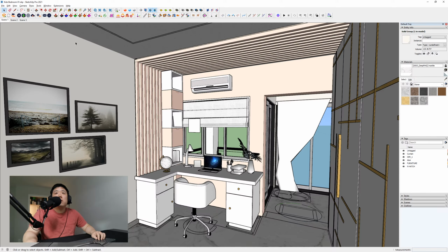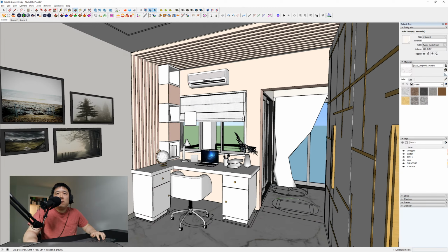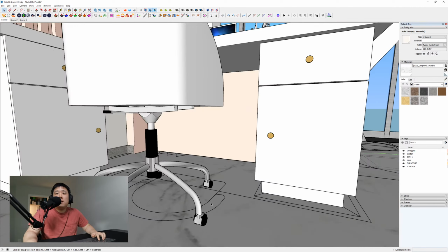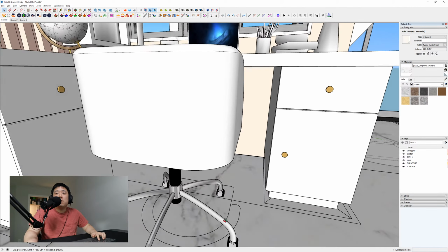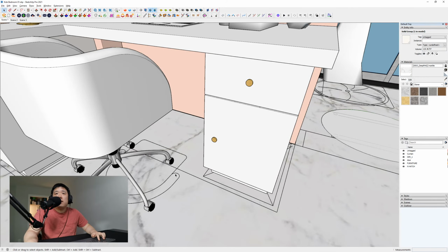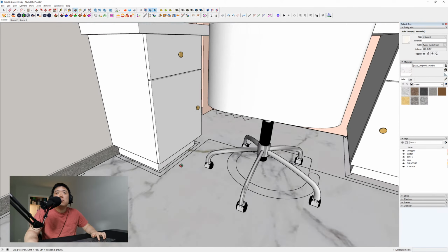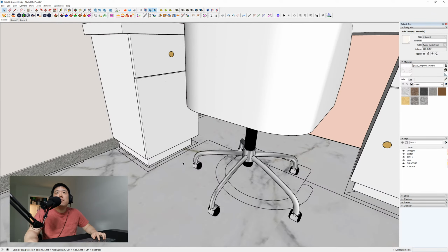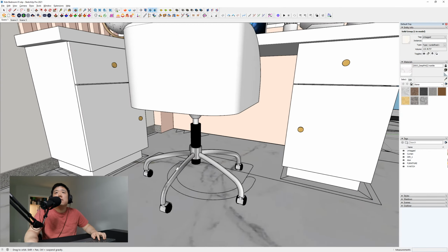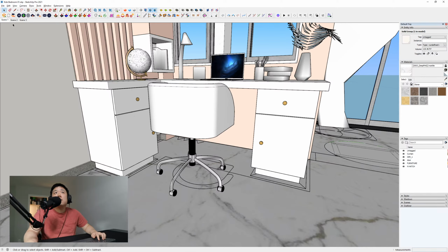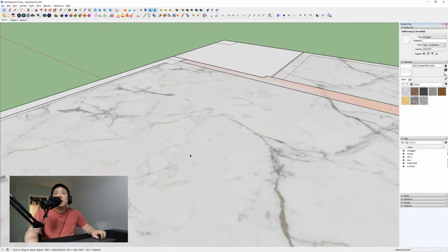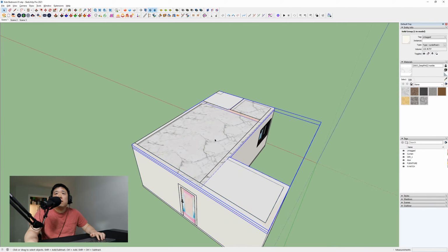And also, I haven't even started Enscape yet, but I'm just doing what I call janitorial work on top of SketchUp to just kind of clean things up. So in this specific scene, whilst I know you can use these CAD lines and it will help with the floor plan lines and with modeling purposes, I prefer to turn them off for this type of rendering scene setup.